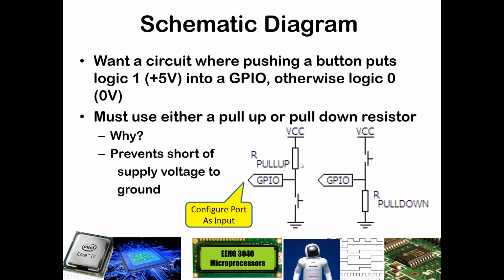So in this case, this pull-up resistor allows us to determine whether our default logic is going to be logic 0 or logic 1, and it also prevents us from having issues of voltage shorting. In this case, we have a pull-down resistor, and this will behave the opposite way. So when the switch is not closed, now we have a resistance pulling down to ground. There still is going to be no current flowing through into the GPIO pin, and so when this switch is open, we are going to see a logic 0.